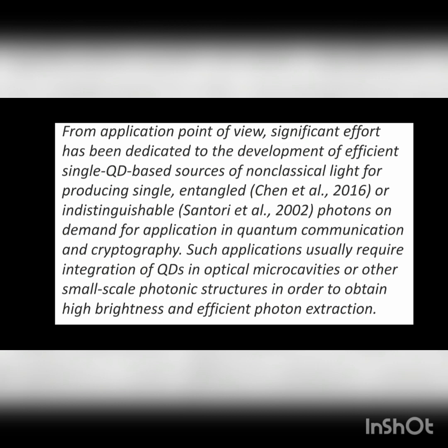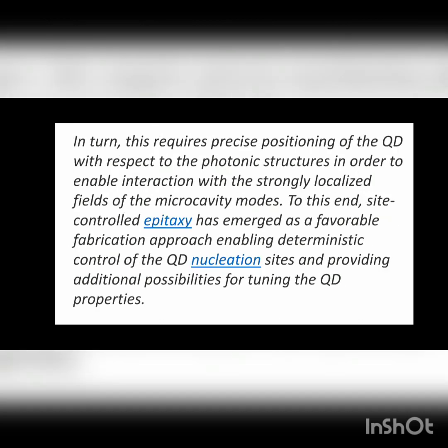Such applications usually require integration of quantum dots in optical microcavities or other small scale photonic structures in order to obtain high brightness and efficient photon extraction. In turn, this requires precise positioning of the quantum dots with respect to the photonic structure in order to enable interaction with the strongly localized field in the microcavity modes.